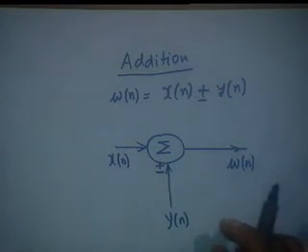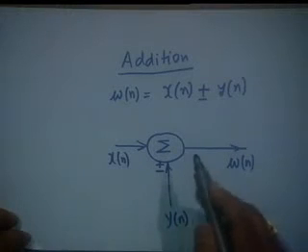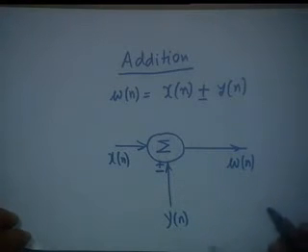One more point that needs your attention is that in digital signal processing, as you know, in digital hardware we cannot add more than two numbers at a time. In the accumulator, we feed numbers in sequence and it adds the number, replaces the storage by the result, then takes another number and so on. So this discipline we must exercise. In other words, whenever we have to add three numbers, or three signals, we shall use two summers to indicate the steps that are involved. All right.